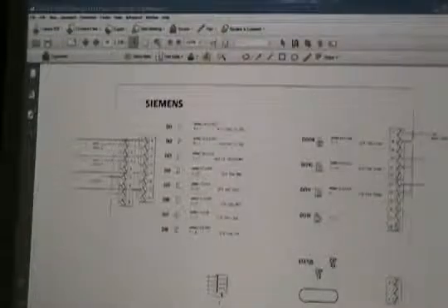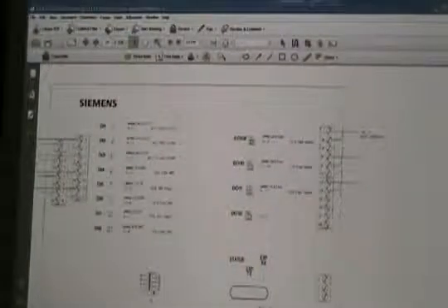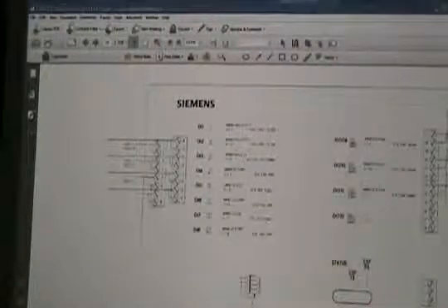That panel has, like I said, a certain number of points. We got an air handling unit that loaded that panel up, so we've got to go to an expansion block. This is a DI expansion block with DOs. So we'll fill out all the points left on that air handling unit. We put this expansion block here, and then we've got another one down below here that's going to have analog devices on it.